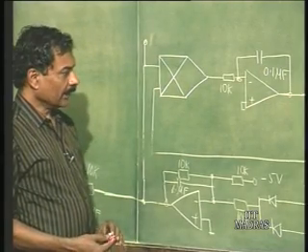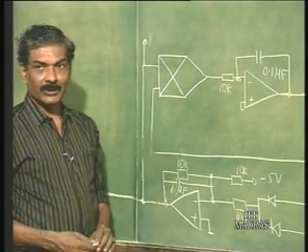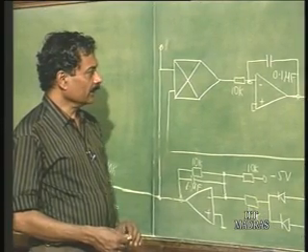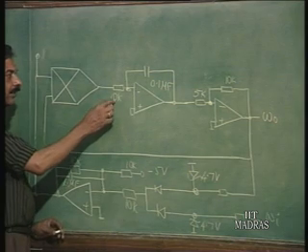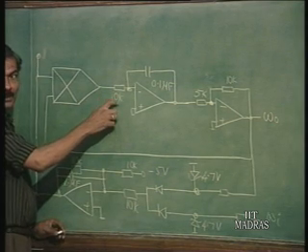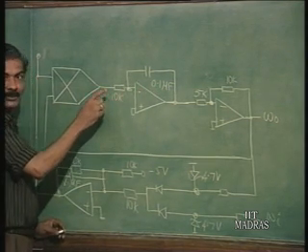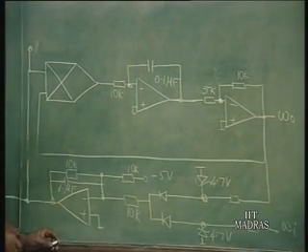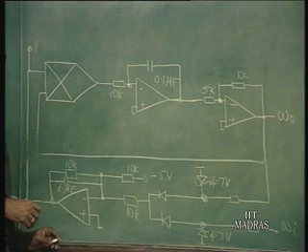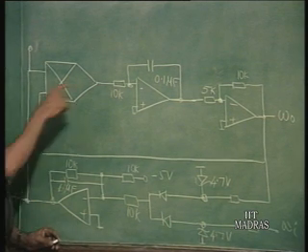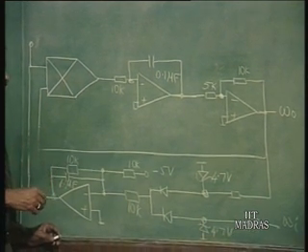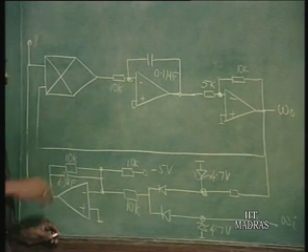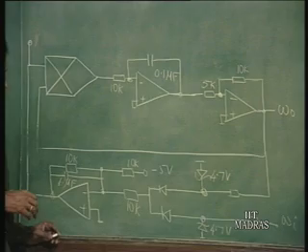The phase lock loop that I have designed here, which is going to be demonstrated, is exactly similar to what we did earlier. Only thing is, it is oscillating at a lower frequency. Earlier we had put 1K and 0.1 microfarad. Now I have put 10K and 0.1 microfarad, so that the free running frequency is one order of magnitude reduced. Because these op amps are such that the waveform that you get as a square wave was not good at high frequency, I had made it operate at lower frequency for ease of demonstration.